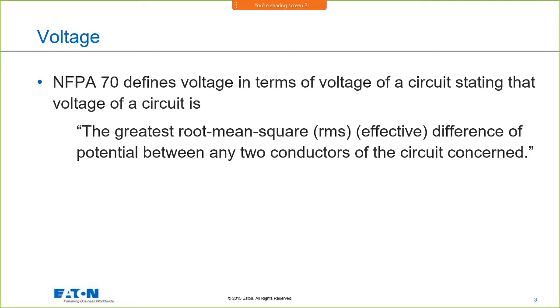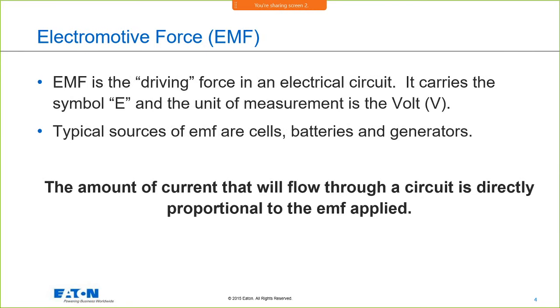going to be comparing voltages, and when I start putting handle ties on breakers and things of that nature, I have to make sure that they are still being applied correctly based upon the maximum potential between any two conductors of the circuit concerned. So we're going to get into a little bit of that as we move down the road.